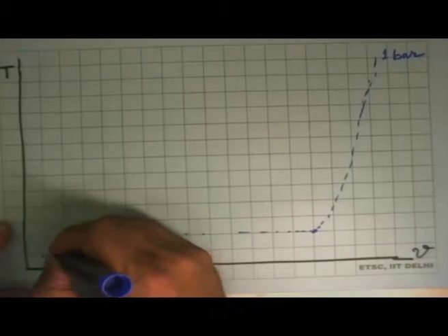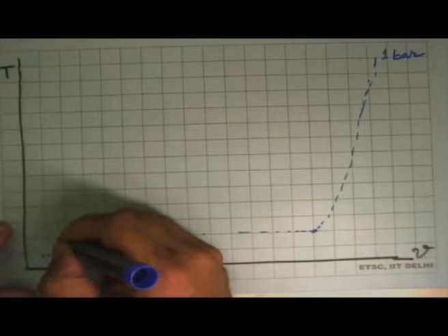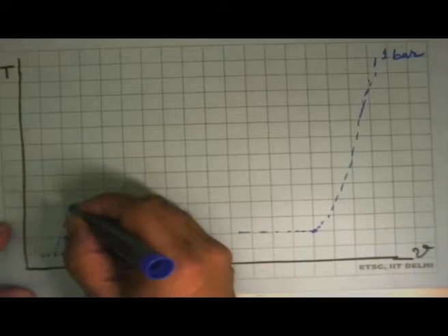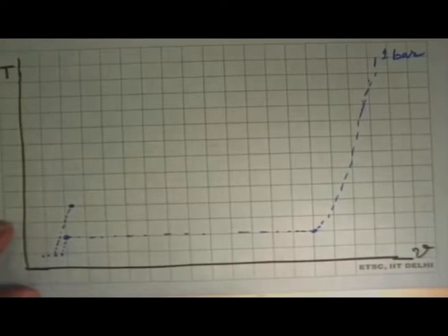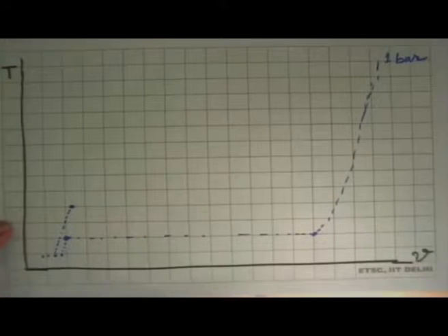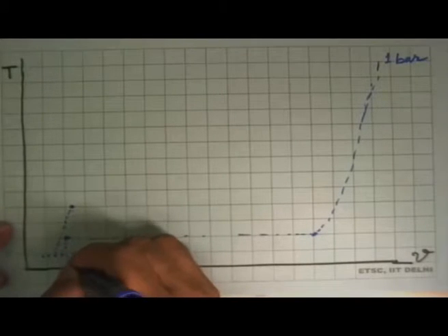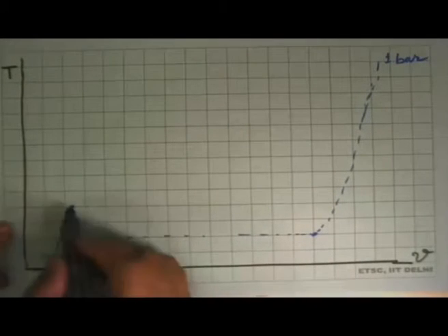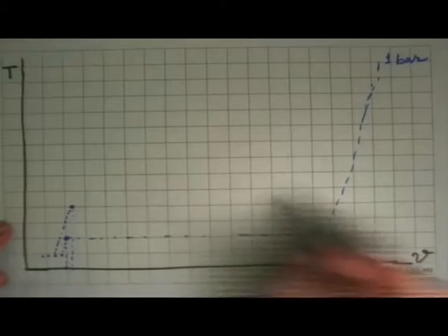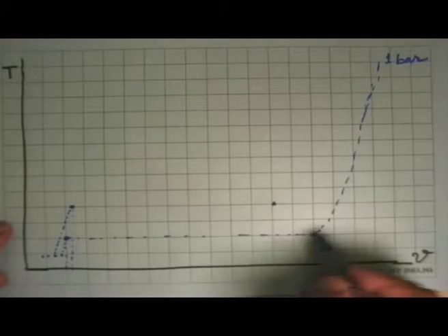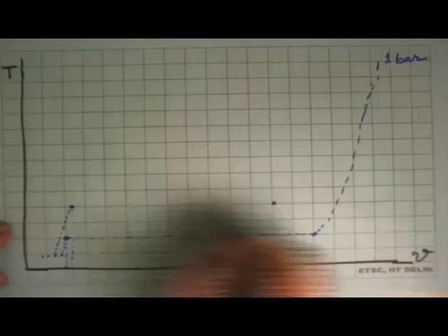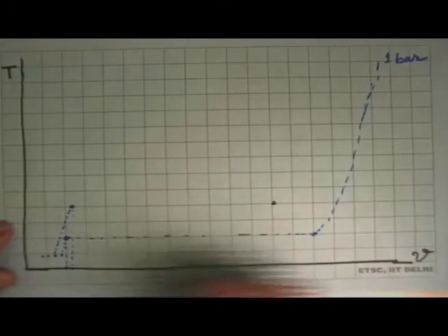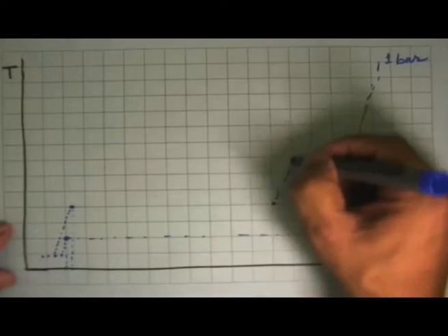Now we heat this liquid, and what we see is that this goes up here, and the temperature at which the phase change begins has now increased, and the specific volume at which it is happening has also increased. It changes phase, and it is somewhere here that it becomes completely a vapor phase, and then from here it goes off.